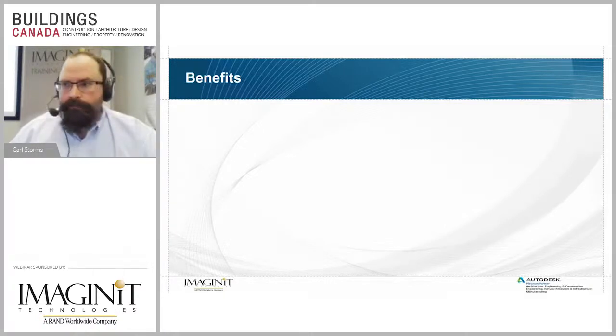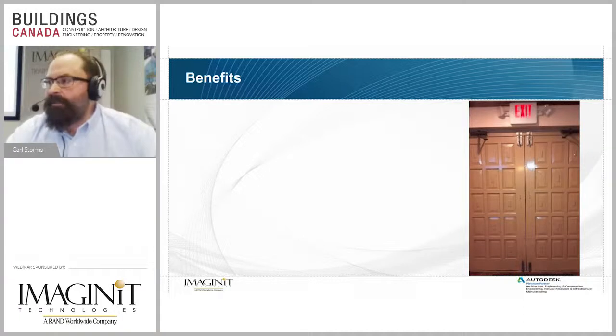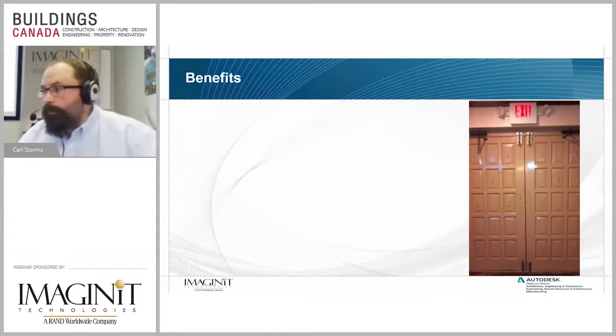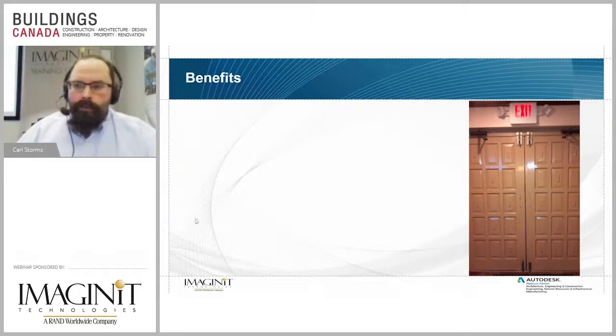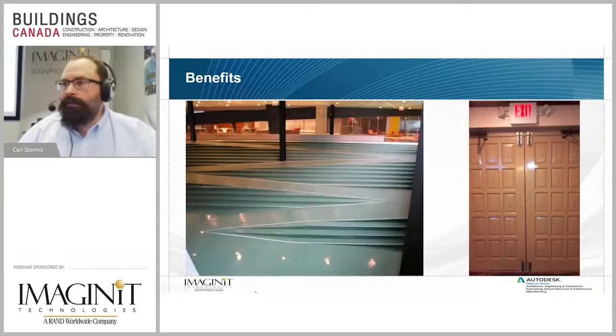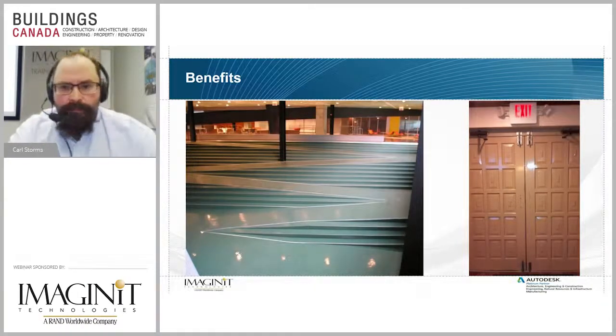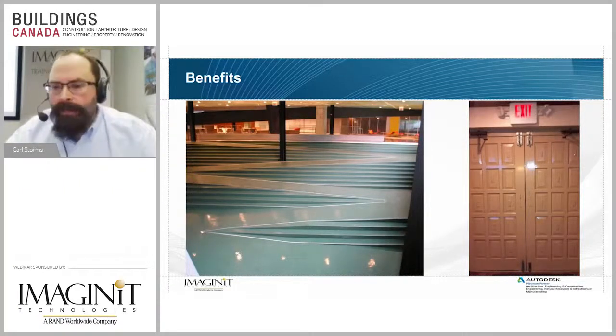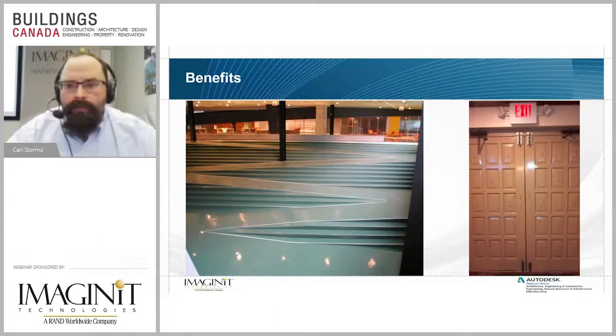And a case in point is this lovely exit door here. We've got some deadbolts put in place, but we don't have our emergency escape bar in there to get out. So of course we want to make sure that we're not in that situation. And we also have the ability to take a look at these stairs, the trademarked and famous Rem Koolhaas ramp with no handrails. Well, it gives you a bit of a funky look as you're going through and seeing that. It's also certainly not going to pass code because we have no handrails there at all when we're working on the stairs. And these are the sort of things that we try to take away when we're dealing with code, and we try to solve that.